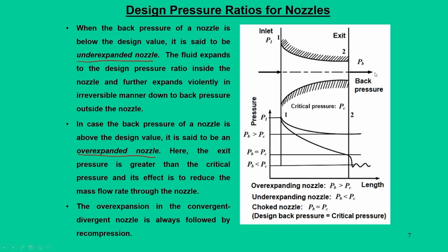So, there are two types of nozzles, one is under expanded nozzles, the other is over expanded nozzles. Then what does this mean? Let us see when we have choke conditions. We have the inlet pressure, the back pressure PB, and what I am interpreting as the exit pressure. Let us say it is at PC, that means we will achieve these sonic conditions at the exit.